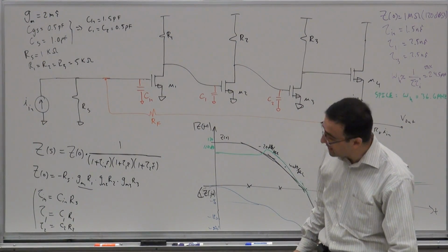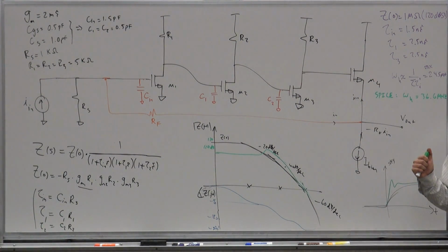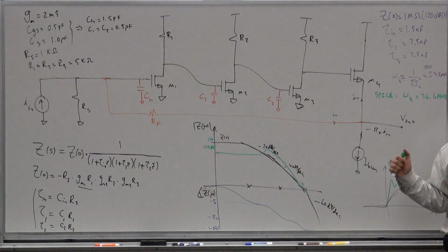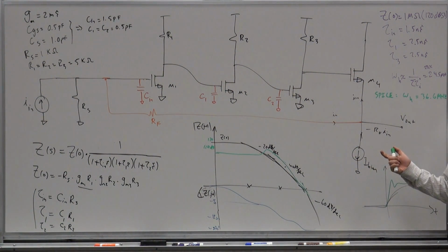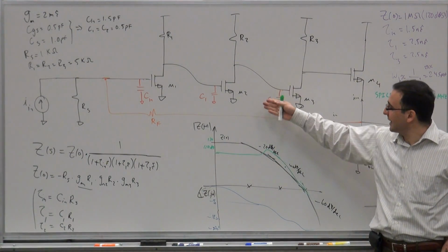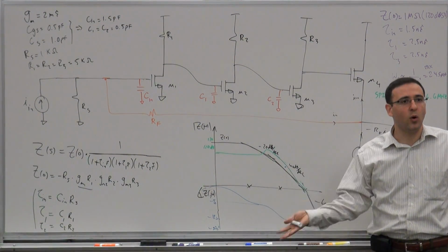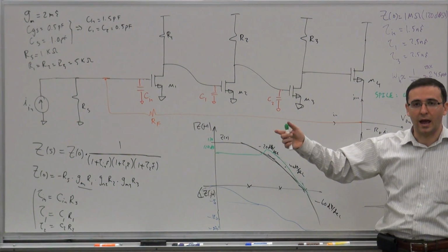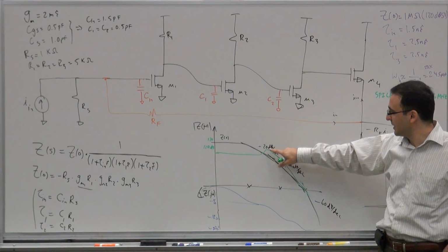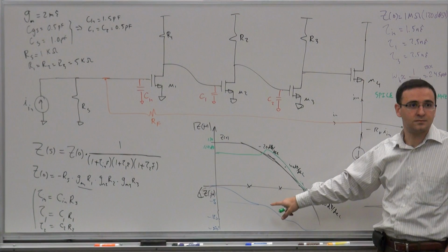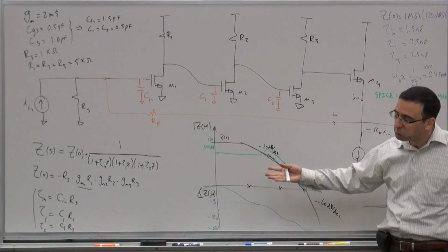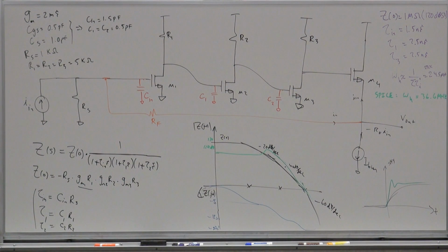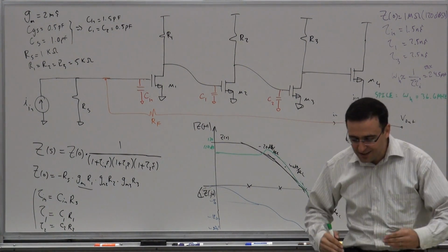But the main point is that as soon as we apply feedback, and we will analyze this in more detail in a few minutes, you saw this. You had a circuit that had 3 left half plane real poles, and you apply just one resistor of feedback, and now you're creating things that clearly have complex poles. Okay, fine. And this is not the first time. We saw this when we were doing the analysis, a couple of cases with the time constant, where the poles would move when we were doing feedback. All right, fine. But now let's go a little bit further.